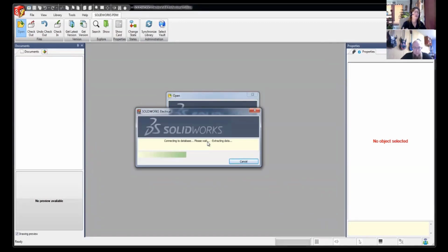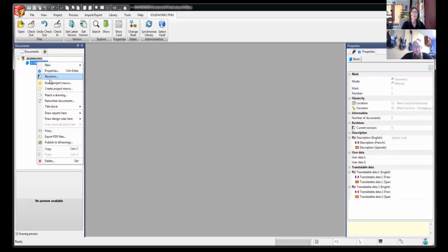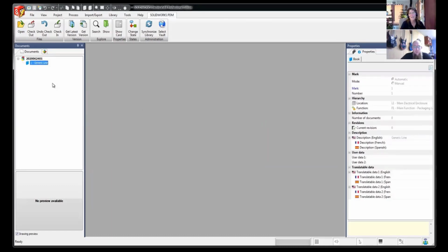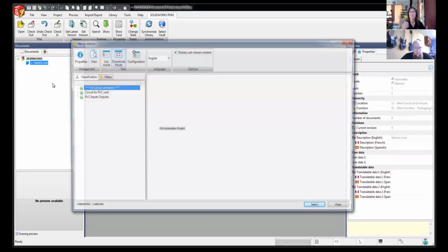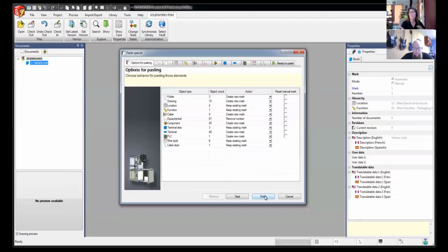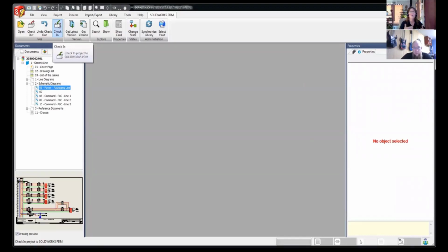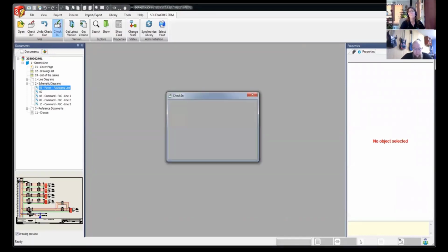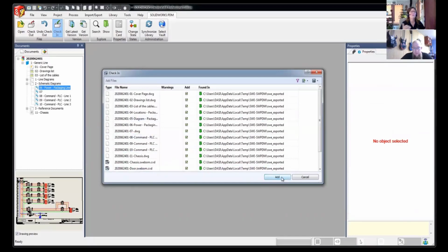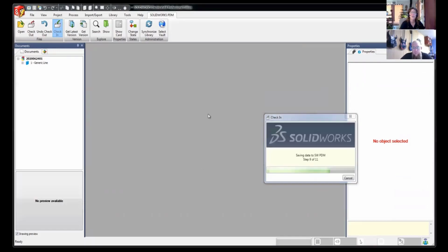This process then allows you to now have some more control than what you had with the other areas. Now this template we made without any data in it. So that way it was very flexible. Now, one thing you may want to consider is having multiple projects in your project template, or in your PDM template, I should say, because then you could pick or choose which one should be applied depending on what type of job this is. We created this one that was empty, so that way it was flexible for all, and then just used a macro to drop in some data.